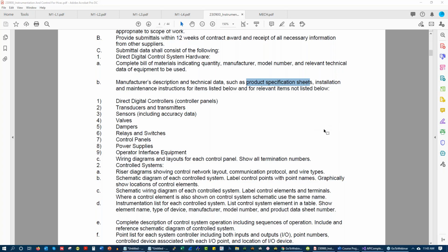They'll go through the test plan, and it's called a functional test. They will validate documents, they'll validate design, they'll validate functional test according to their test plan. And if you pass it, great. If you don't, you have to fix the issue, remediate, that's the word I was looking for. You have to remediate any of the deficiencies. Then there's informal commissioning, which is basically just glorified point-to-point, where you're going through and doing a point-to-point check internally. So that's kind of the difference.